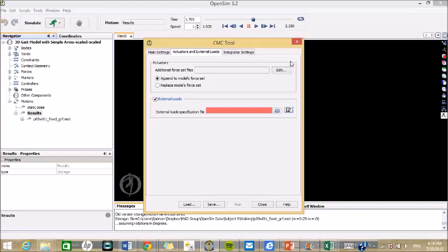The first fix is to make sure that you have your additional set of actuators applied here, or added in, and I showed how to do that earlier. The other thing, if you've already done that and you're still having problems, is that the muscles themselves in the default model may not be as strong as they could be.